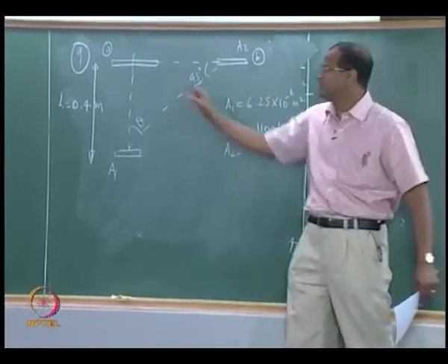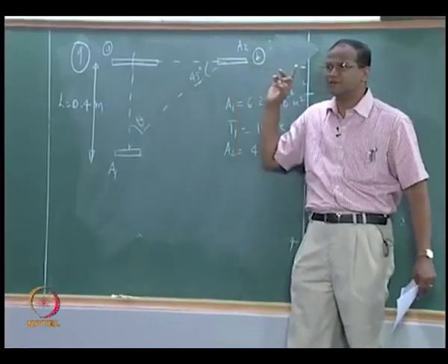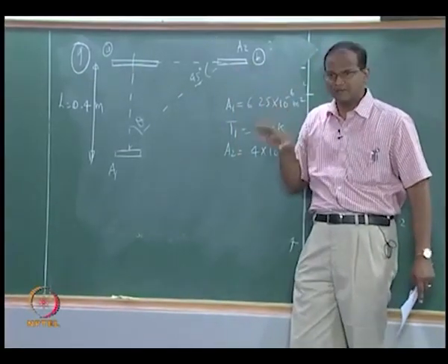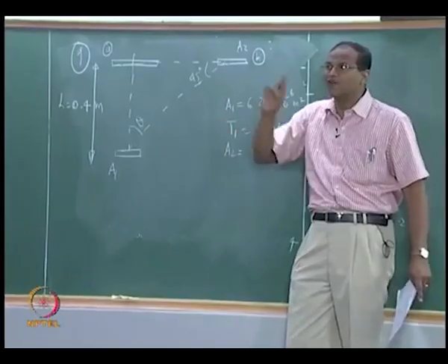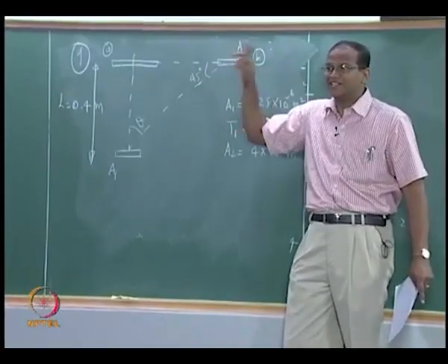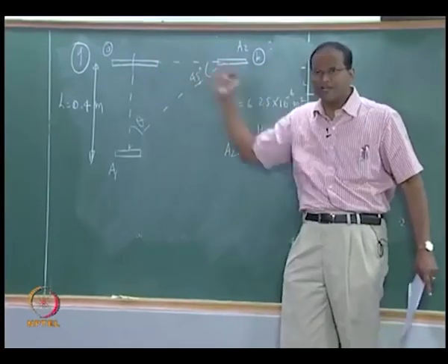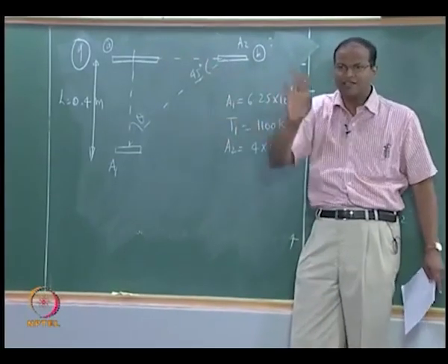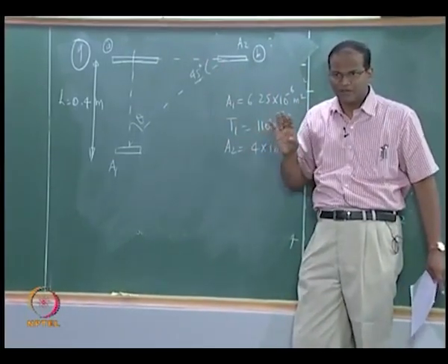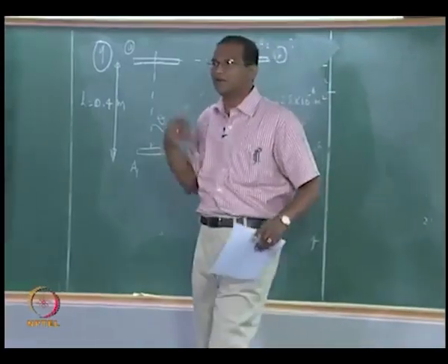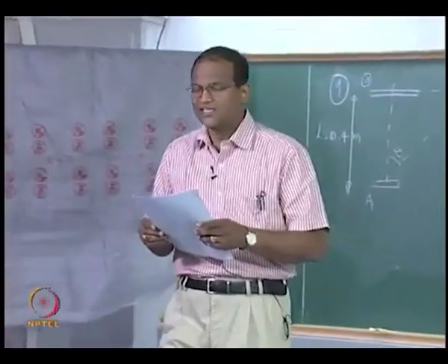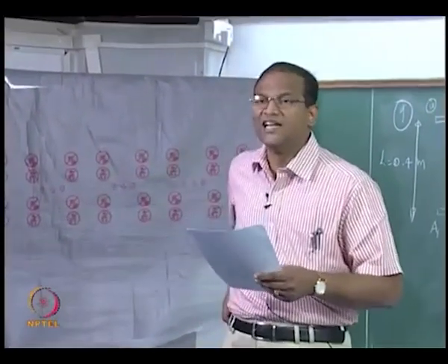If the emissivity in position A is different from the emissivity in position B, then it is not a diffuse emitter. But even if it is the same, we do not know whether it is the same in all directions, but at least you can say between 0 and 45 it has the same value. Are you getting the logic? Now I will give you the data, you can take down the problem, okay. Consider an arrangement as shown in the figure to detect radiation.